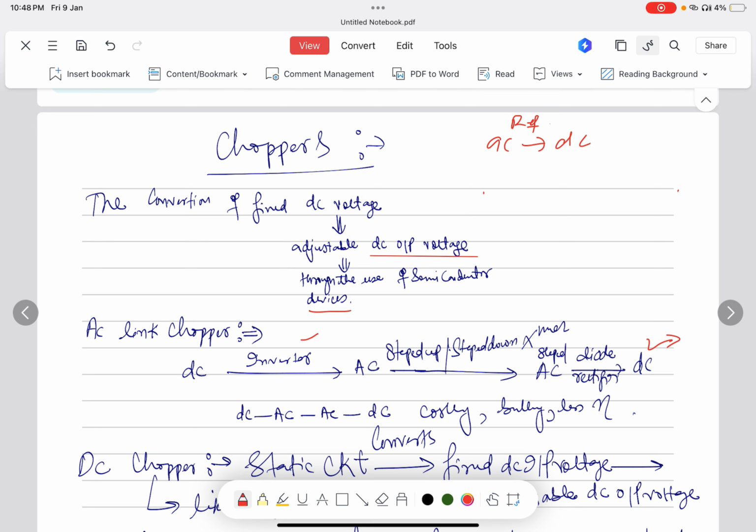So the question arises, why do we need DC? In industrial applications, as per the usage, we have subway cars, trolleys, buses, battery operated vehicles and battery charging. All require DC. So how do we get it? By the rectifier or phase controlled rectifiers. But the problem here is that to control the subway trolley or battery operated vehicles or braking, we require a variable DC. So for a variable DC, we focus our interest on choppers.